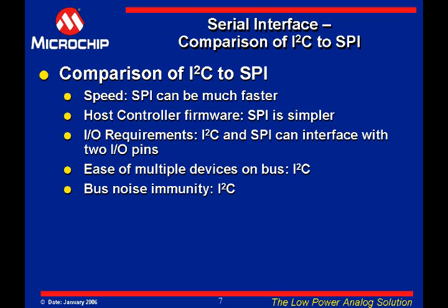With respect to I/O requirements, both the SPI and I2C can be done with 2 pins, but the SPI interface would not be at full functionality since the host controller would not be able to read the device, and the device would always be selected since the CS signal would need to be tied active. The I2C protocol only requires 2 signals. These are the SDA and SCL pins, and the address pins A0, A1, and A2 can be tied to the desired state, which could allow multiple devices on the bus.